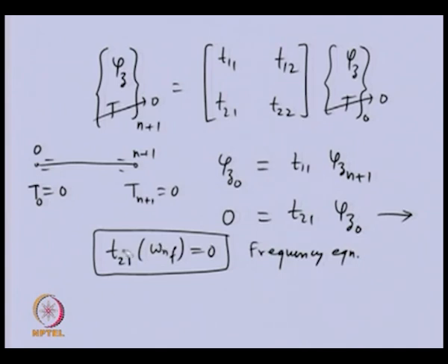This will be in the form of a polynomial, and we can solve for a simple system using the polynomial solution, or by some root searching technique we can find the various natural frequencies of this particular equation. Second, this particular equation, once we obtain it, can be used for obtaining the field variables related to each other, so that we can draw the mode shape.